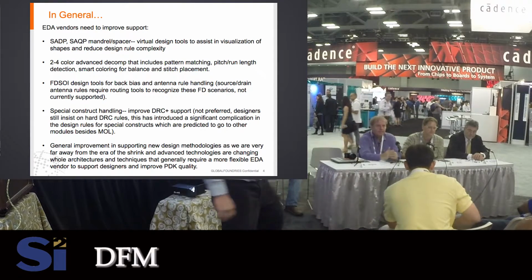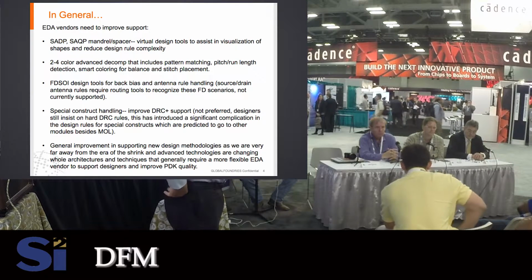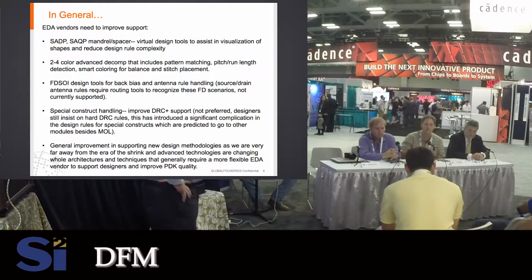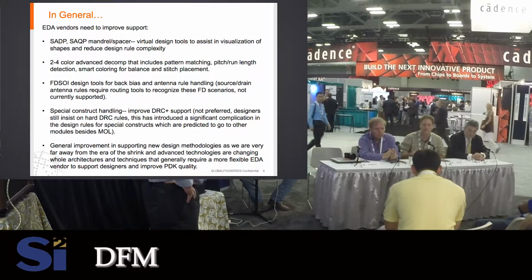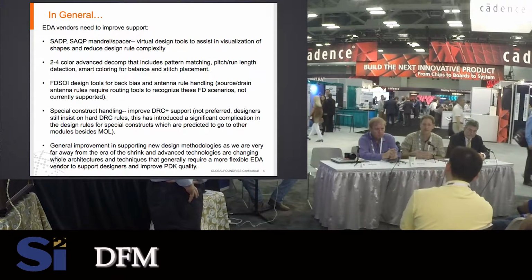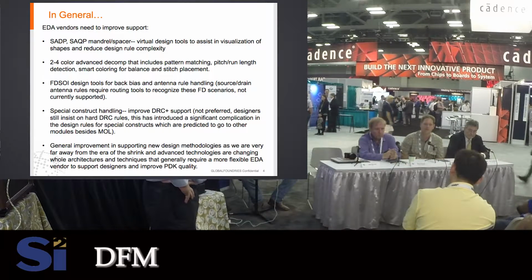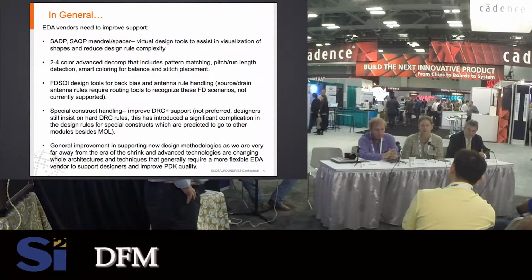For example, if my voltage is 2 volts, 3 volts, 5 volts, how do we design the spacing, how do we specify the spacing when we design the design rules? Right, so that is just an additional rule. Raul showed the number of rules that you have in a rule deck. It's just one additional rule to everything that you have for can this design be manufactured. Now you're taking that voltage into account, where it's not just manufacture that you care about, it's the lifetime of the device. How are those oxides between those layers going to hold up over the lifetime? So it's a reliability question that needs to be determined, what those spacing rules are for those voltage nets.